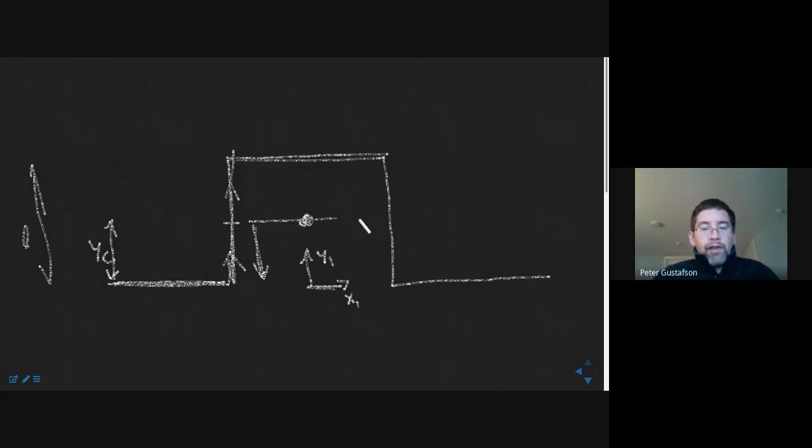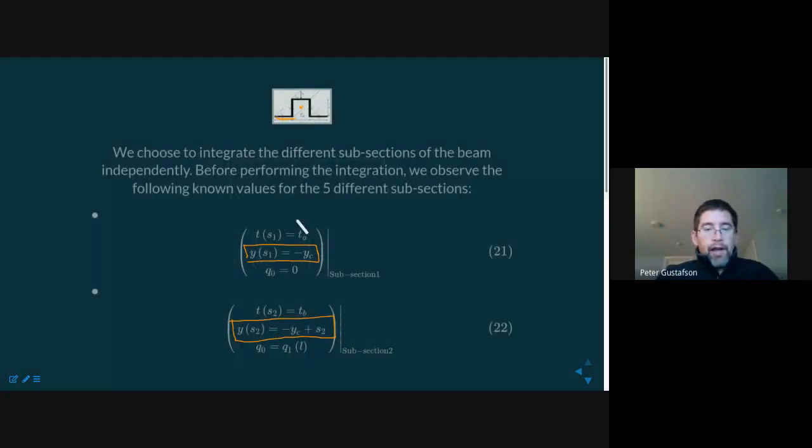Okay, so the distance from here down to the bottom flange is YC, because we're defining our coordinate system of convenience here at the bottom, and we know from the bottom we go up to YC. But the thing is, we don't know where YC actually is. Okay, this is a distance. We know it's a distance. I drew it where it was because I know it's generally in that area. However, I could easily have done this.